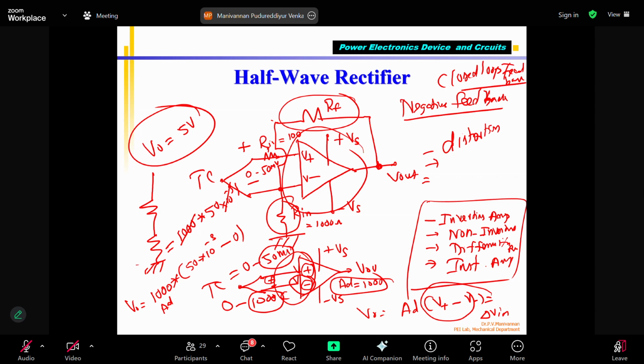Arnasalam, do you want to tell something? What is the advantage of a closed loop amplifier? Negative feedback. Distortion, noise reduction, both they have told. One more thing is the stability, sir. Stability, that is correct. What stability? Less oscillation, sir. Less oscillation. That's correct. More than that.